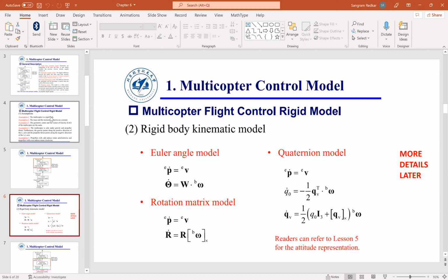Now, I want to say something about this orientation problem because this orientation problem is not trivial. So, if I give you angular velocity, say my UAV is rotating in yaw at 10 degrees per second. What would be its angular orientation after 1 second? Let me repeat. If initially it started at 0 degrees, what would be its orientation after 1 second? You would say 10 degrees. That is perfectly fine as long as these two coordinate frames are aligned.